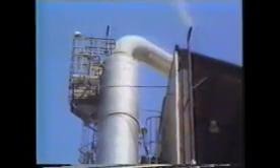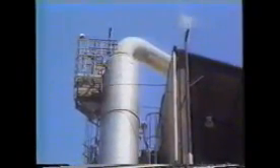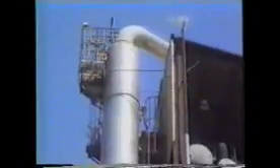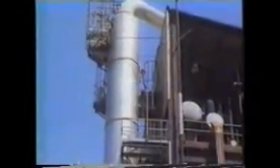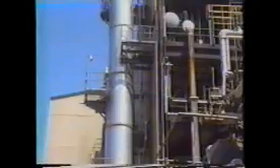Purging the column would be required if the feed mixture were combustible. The primary purpose of purging is to remove or displace the oxygen contained in the column. Purging is typically done with either steam, nitrogen, or carbon dioxide prior to introducing feed to the column. The feed in this particular system is not combustible, so the operators proceed to the first stage.